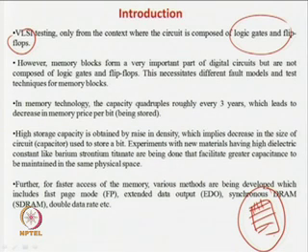One more thing: memory is very symmetric. It has memory cells, you can access the cells, you can read the cells and write the cells, and that is the only thing you want to do. There is no other logical operation involved in the memory. A flip-flop also stores a bit, 0 or 1, but it is also involved in a lot of logic operations. So the philosophy of using a flip-flop and of using a memory is a bit different, even if their job is the same.